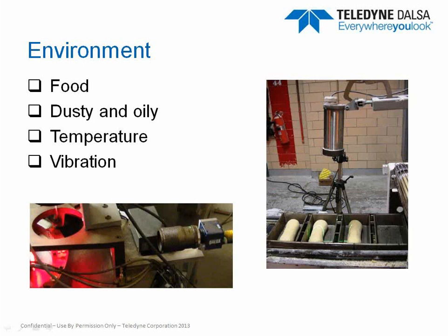Vibration, I usually recommend people to mount the camera on the same kind of mountings where most of the products are going to be running, so they're within the same harmonic. Stay away from like big pounding drives. Usually, people put a structure right to the concrete, and they mount the camera on top to attach to a conveyor. So take into account all this when you are putting your camera in your factory floor.